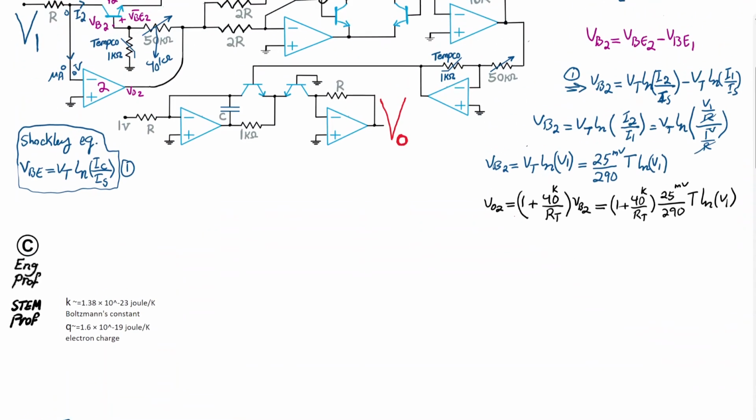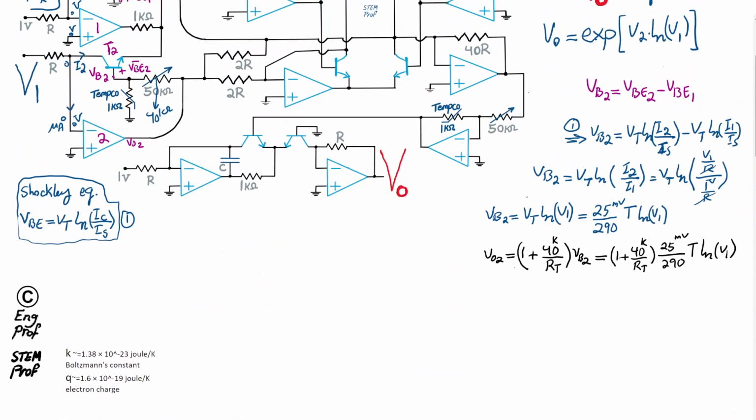So with that, I am going to write, effectively, that RT is equal to 3500 divided by 10 to the 6, that's the meaning of 3500 ppm, and then we have the nominal value of it, which is 1 kilo ohm, and then times temperature. So as a result, RT becomes 3.5 times the temperature in Kelvin. So that's the beauty of the RT. It has positive dependency, linearly, with the value of the temperature.